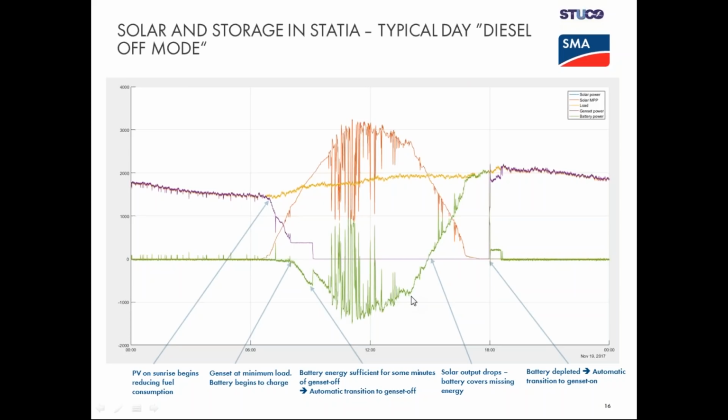easily handled by the battery. All day long until we come here, it's getting afternoon, the sun is getting lower, and the battery stops getting charged, it starts discharging and supplying energy so that the gen sets do not have to be turned on yet. This happens. So there's a point of perhaps 30 minutes to 1 hour when there's nearly no PV in the net, but the graph would be fully blue.